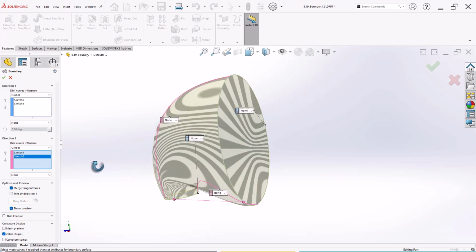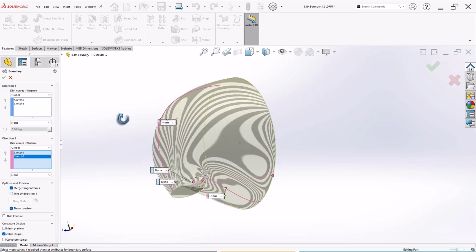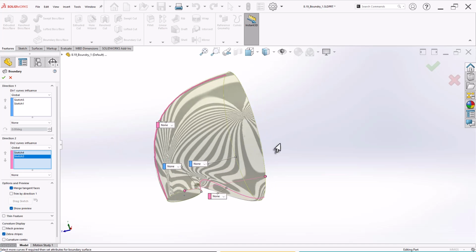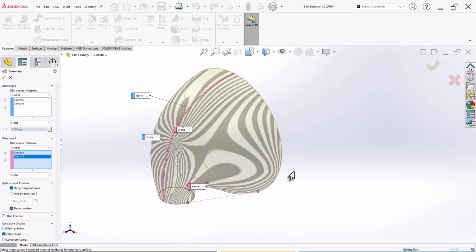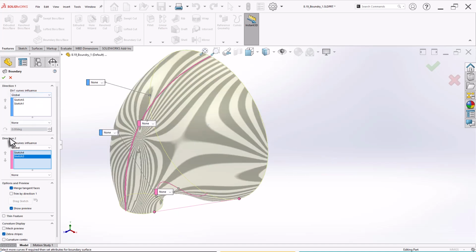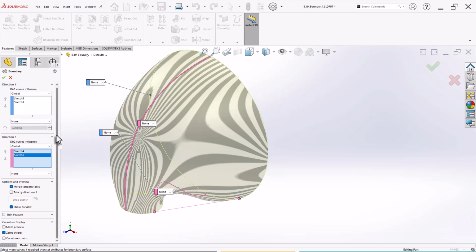So you can say it controls the outer face surface in this direction as well as in this direction using these sketches. Technically we refer to them as direction 1 and direction 2. Because these are curves, it does offer, as explained earlier in the loft feature, influence of next curve, sharp, next edge. Similarly in direction 2. Because of this influence in two directions, it gives a smoother surface compared to the loft feature. So let's go ahead and click OK.